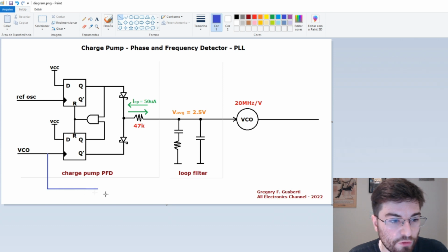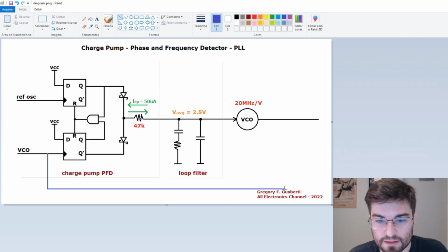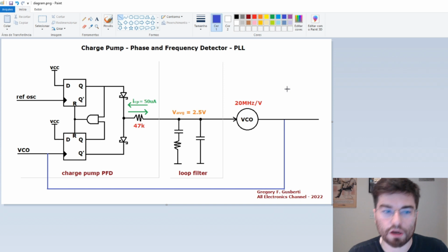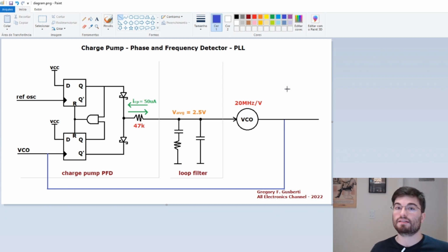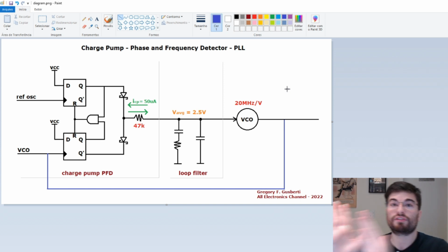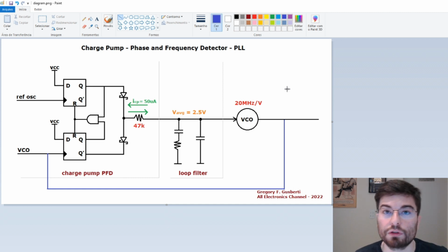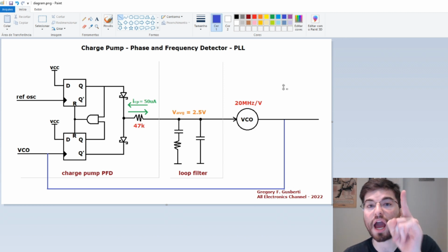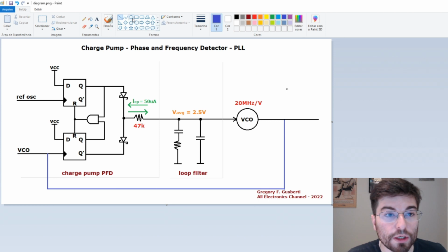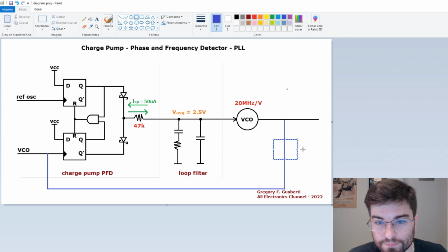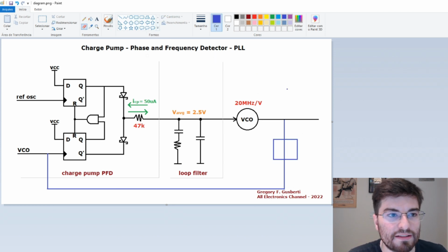The PLL of our design is connected in this manner here, because we are using a sampler, and the sampler down converts, it shifts the VCO output to the correct frequency for comparison in the phase and frequency detector. Okay, if you have a prescaler, we are going to have here a divider that's dividing the phase.